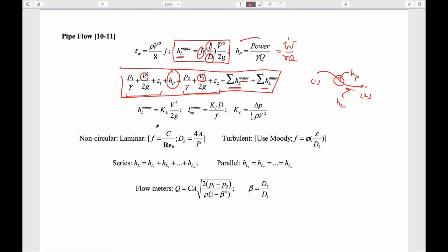The minor losses are at the fittings and bends in the pipe, usually given by a loss coefficient, which is always non-dimensional. It can be larger than one, but is typically less than one. Then the velocity in the fitting, and gravity. Not sure you need those.